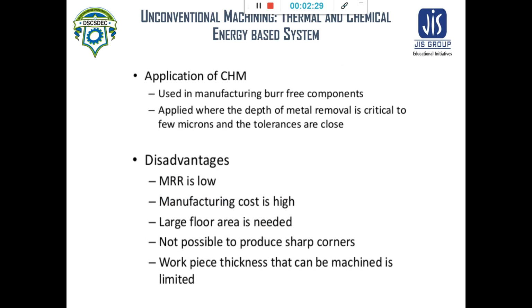Now, the applications of chemical machining. Chemical machining is used in the manufacturing of burr-free components. It is applied where the depth of material removal is critical to a few microns, and the tolerances are close.